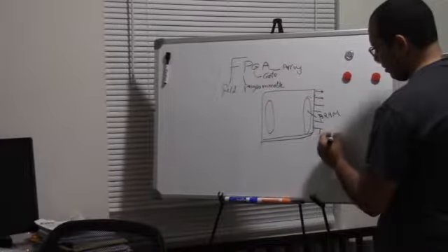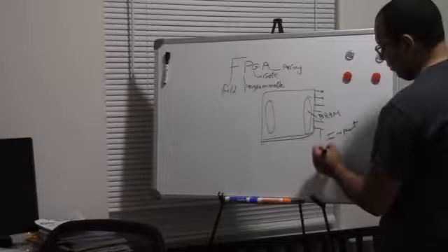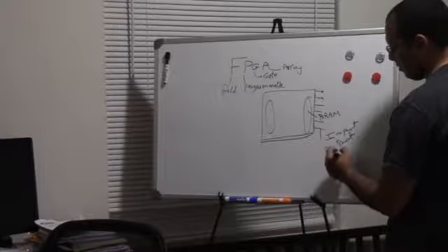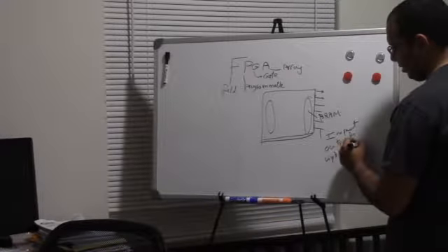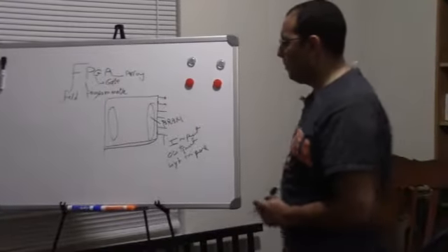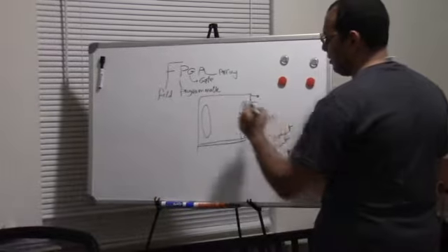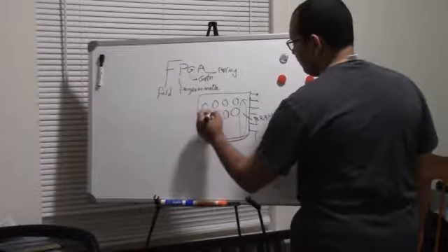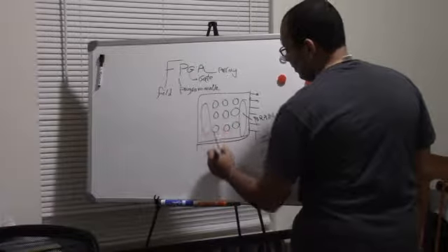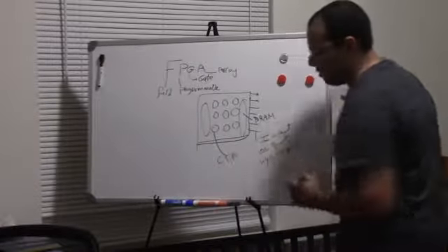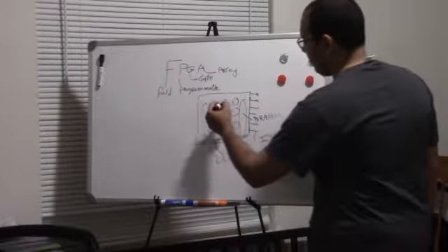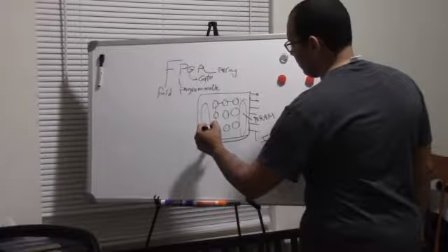be input or output or high impedance. And by high impedance I mean that it is not connected, or maybe can be connected for a different purpose. Okay, inside the box you will find a couple of small tiny blocks. Each of them is called a CLB, a configurable logic block. Okay, those can connect to each other using connectors or wires.